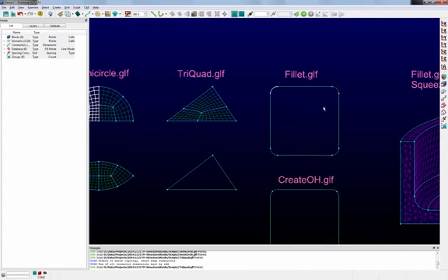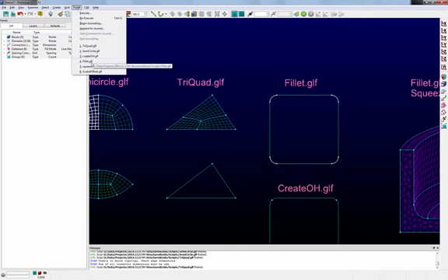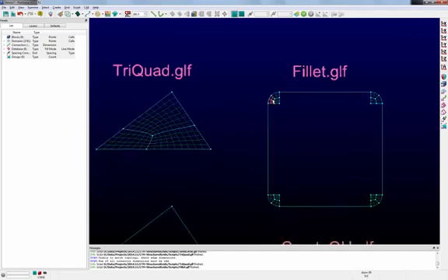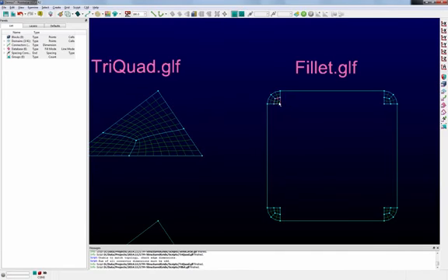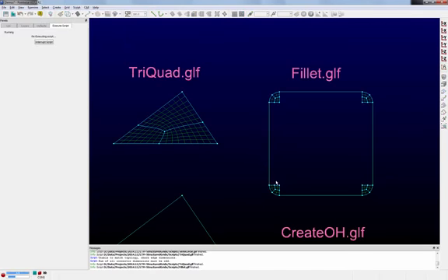So the first thing we're going to do is create these little corner blocks, as I call them. You simply highlight these connectors here. You then go to script and run this script that I've named fillet. Whenever we run this script, it's going to create these quadrants for us based on this local curvature. Then we can run another script that I'll talk more about later that will take these other connectors and fill in.